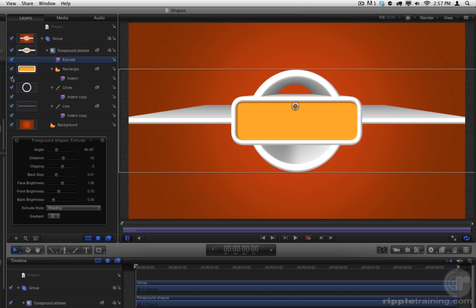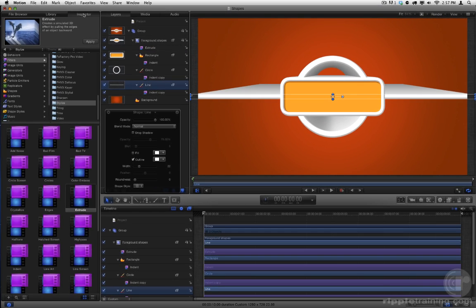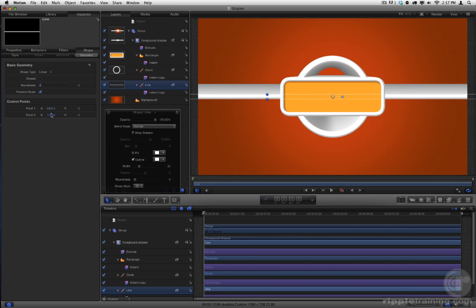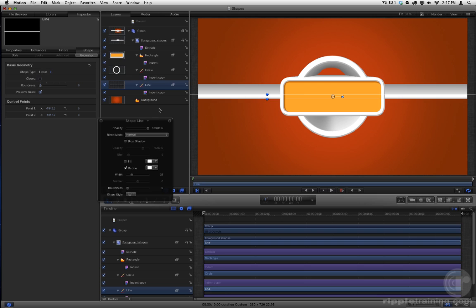The line now needs to be longer so we don't see its edges, so return to the Shape Inspector, to the Geometry pane, and drag in the 0.1 and 0.2 X value fields to extend the line off the canvas. That's an interesting look. Let's try a few more.